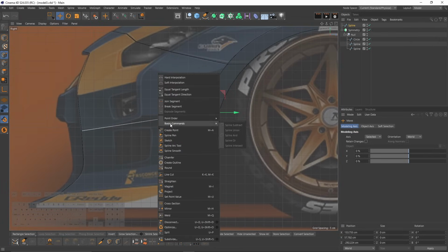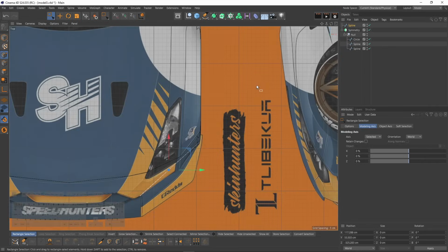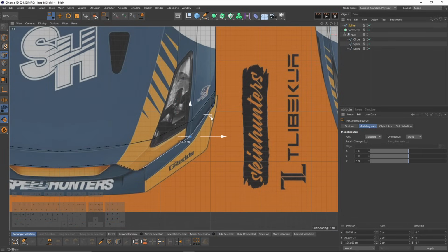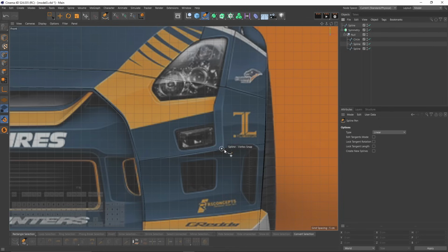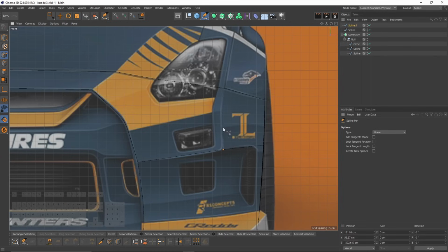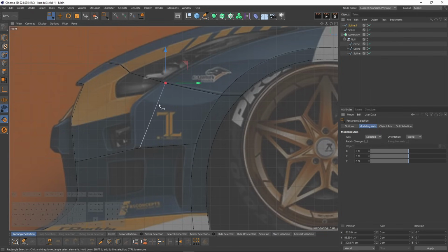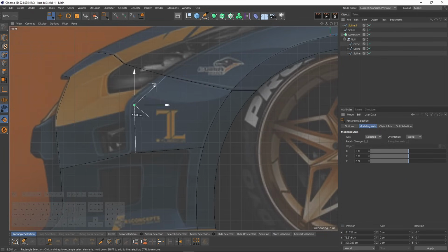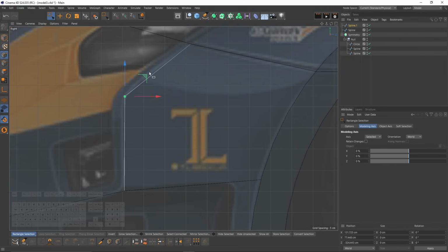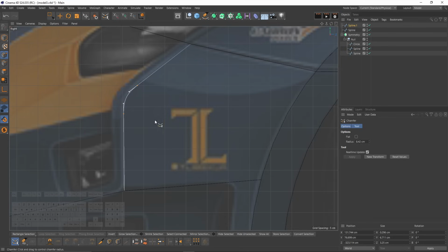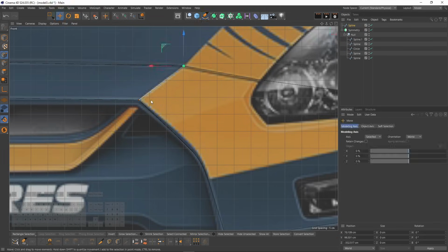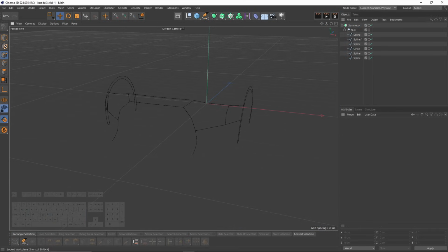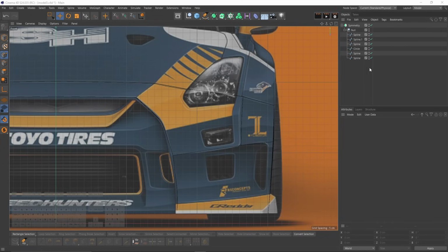Now let's make a cut. Let's right click, select line cut, cut here, then move. After that, let's go to top view and move it right here. Let's create a new one. Click here, after here, then let's switch to right view, make a new cut, then move that point to here, and this one to here. Then let's make a chamfer. Also, let's not forget to put them in that symmetry group. Another one right here. I guess I have shown you everything about the spline placement.